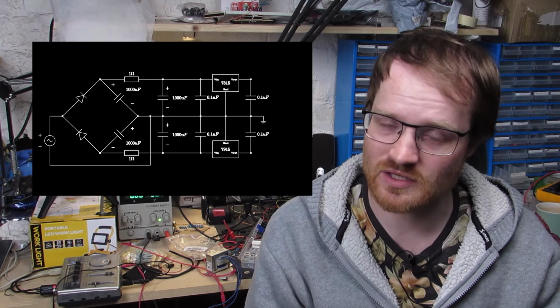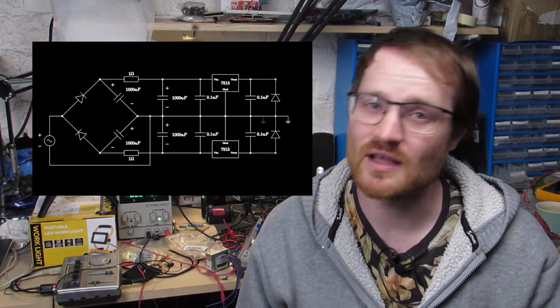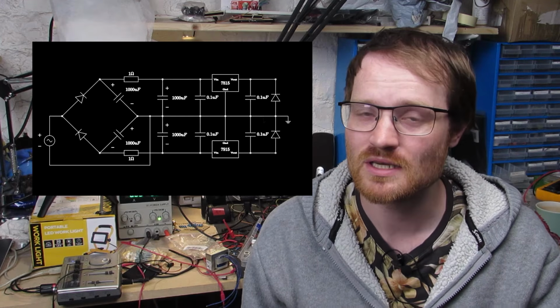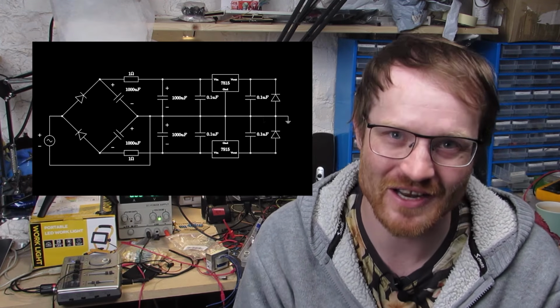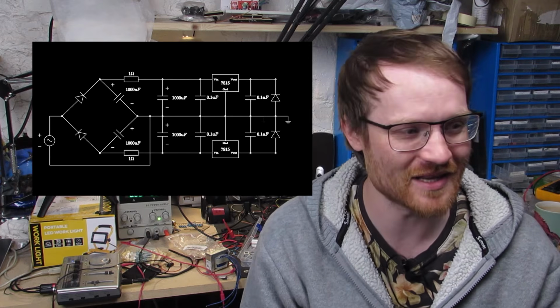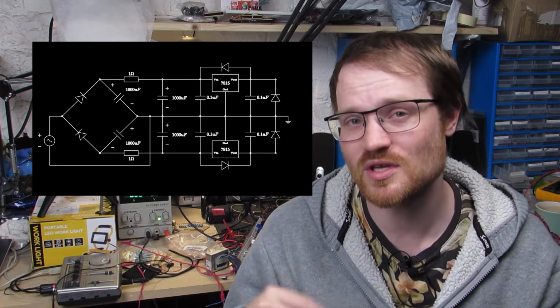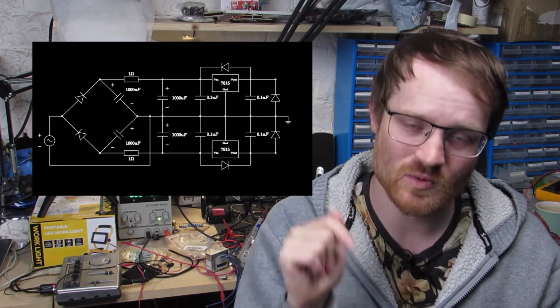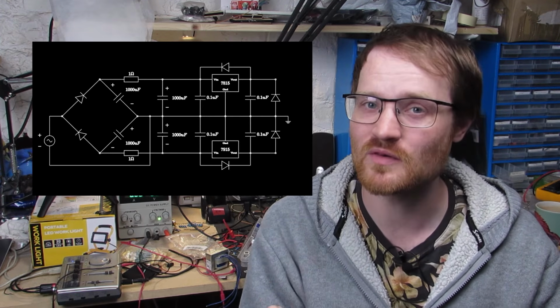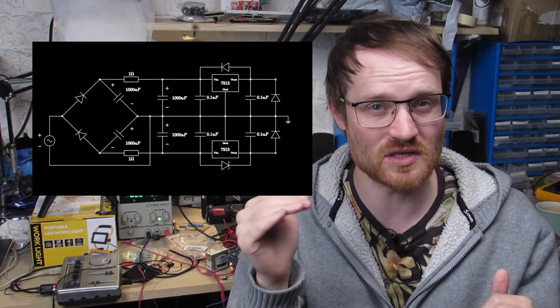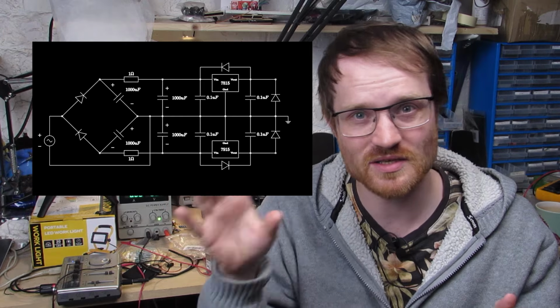And we're going to put some diodes in for safety. So these prevent latch up, which is basically a temporary short to ground can become permanent if you don't have these diodes in place. And these other diodes are a little bit more subtle. These will basically short circuit the regulator when you switch the power off. So when you switch the power off, there might be a period where the input voltage drops, but the output voltage is held constant by the capacitance at the output.